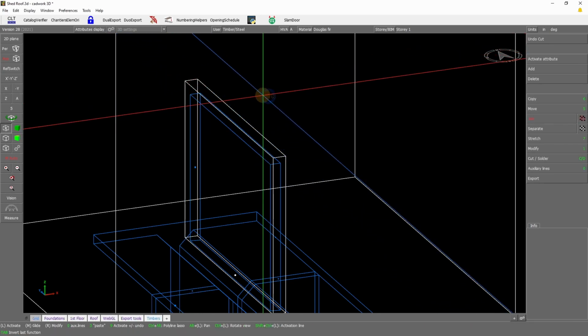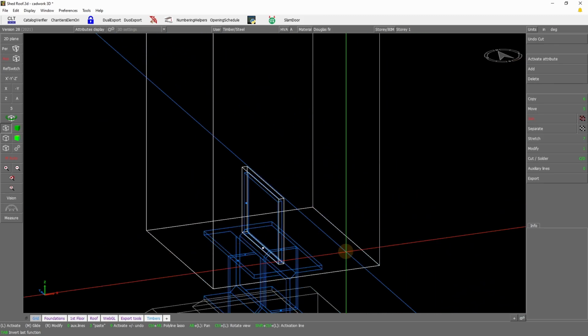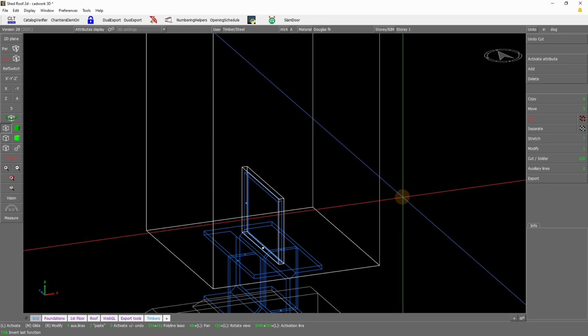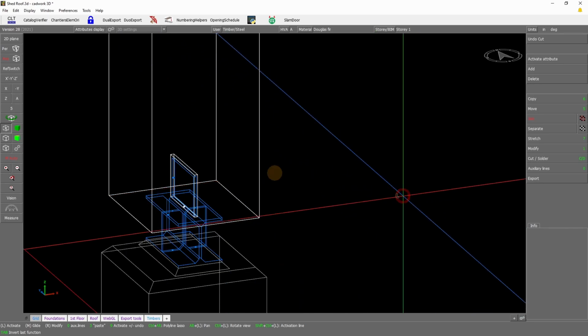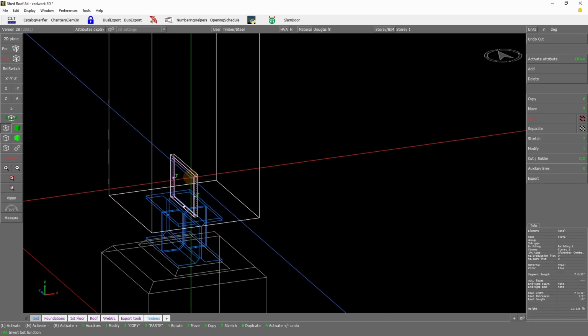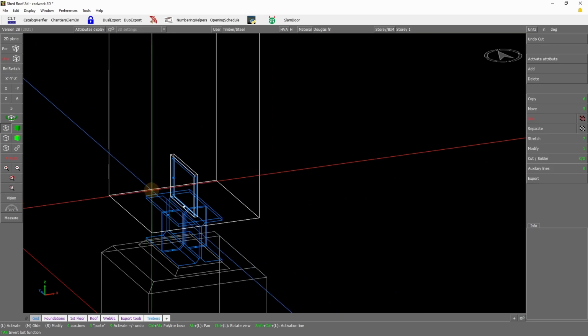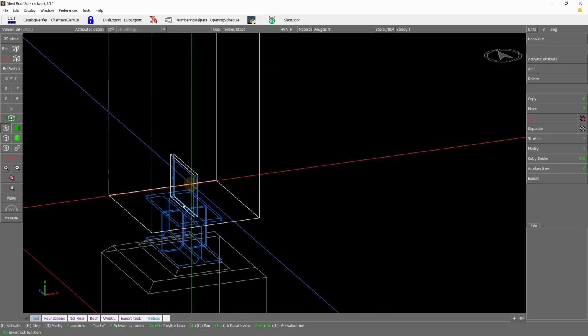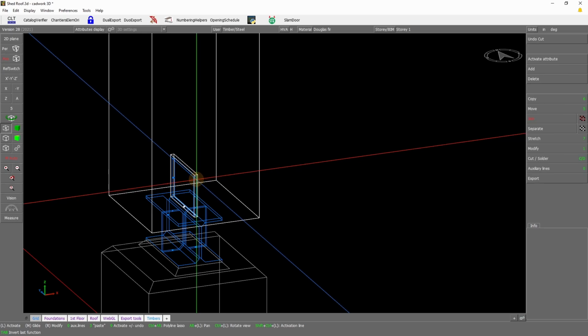So everything is correct. Now that we have all the elements and we no longer have any collision, we will be able to add connector axes, because connector axes cannot be added when crossed elements are colliding with each other. So here we will add the tight fit pin through the knife plate. We want to have the knife plate as reference, so we will need to select it.